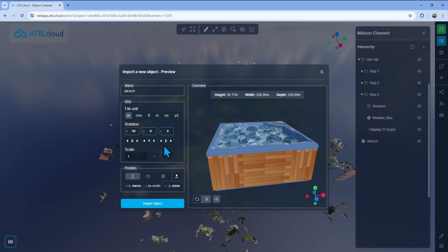So what I'll do is create a simple structure that's going to fill those gaps. So for example, if I want to fill the gap that is at the bottom, I'll just create a simple box that has the same color as this at the bottom. So here I called it bottom front. If I enable it, I have just another box that is right here and perfectly aligned. Okay, if we take a look at it, if I press Control to select it, you can see it's perfectly aligned with the rest. So it's just a box that is going to visually close the gap. That's it. It's as simple as this.